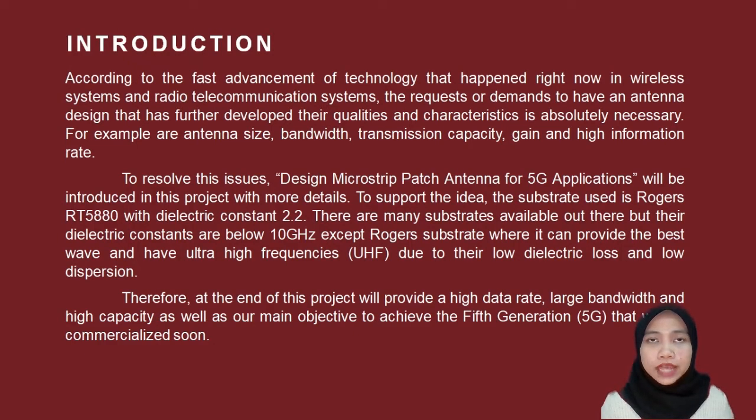To support the idea, the substrate used is Rogers RT5880 with the dielectric constant 2.2. There are many substrates out there, but we chose Rogers because it can provide the best wave and has ultra high frequency due to its low dielectric loss and low dispersion. At the end of this project, we will provide a high data rate, large bandwidth, and high capacity, as well as achieve our main objective of 5G that will be commercialized soon.